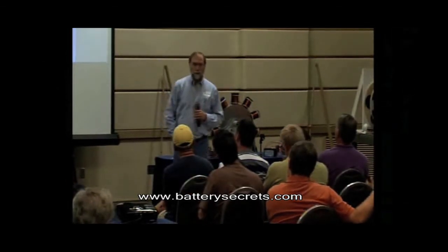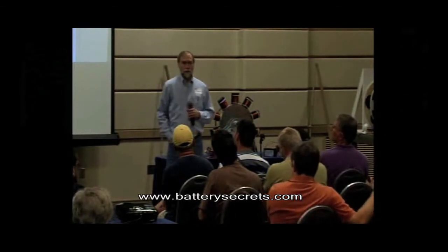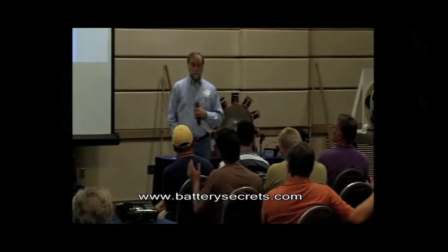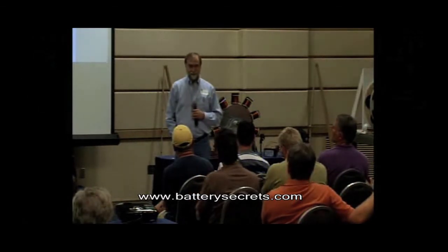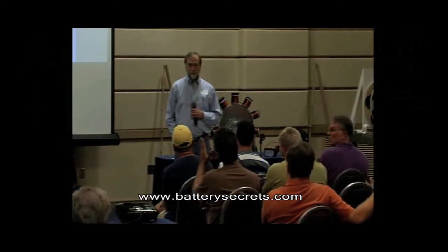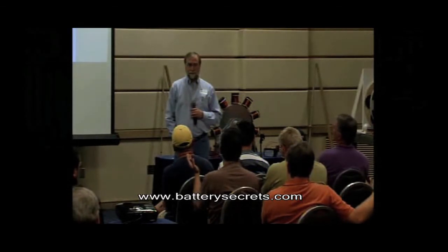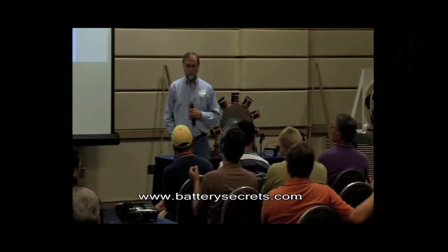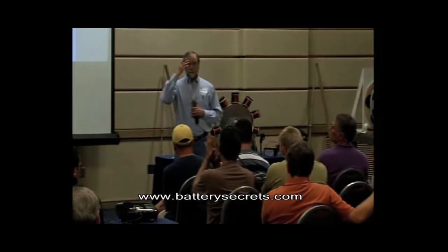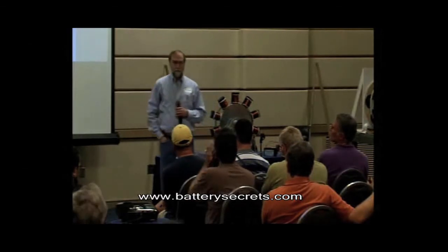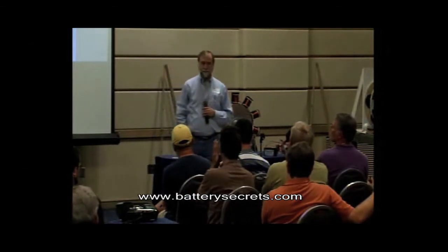I've got some Exide batteries. They're the 2.2 volt, 1060 amp hour batteries. The cool thing about them is they're clear. You can actually physically see the plates. Now, I did observe that the batteries are about 20 years old, and I noticed that the one positive plate has all the layering, and some look like little layers of paper on the edges of the plate that are falling off.